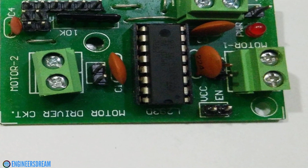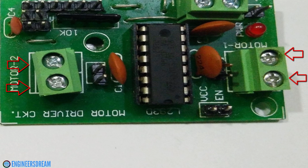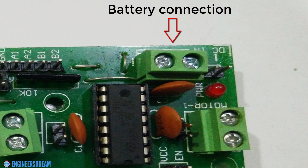The 2 green sockets at the bottom are for connection to the DC motors. So, the output pins of the motor driver IC, that is pin number 3, 6, 11 and 14, can be accessed from these green sockets. Each socket consists of 2 holes in which we have to insert the DC motor wires. And you can also see the green socket which is present on the right hand side is used to supply external power to the motor driver using a battery.